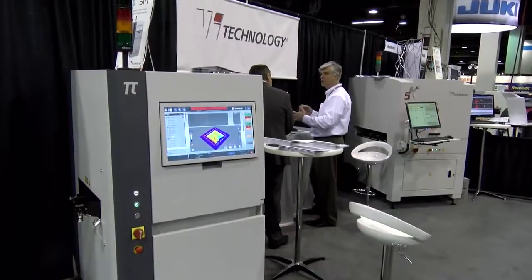So we developed a software tool that allows us to review both sides at the same time. When that board gets to AOI and it shows you a failing component, you can now see what it looked like when it was first printed. And if you made the decision to allow that deposit to pass your printing process, how did that affect the outcome at the end of the line, at the end of the oven?